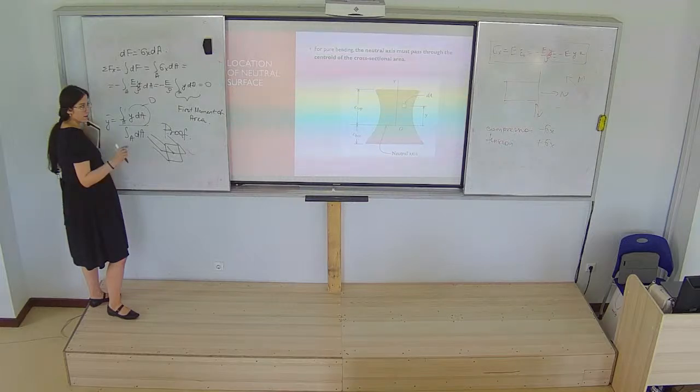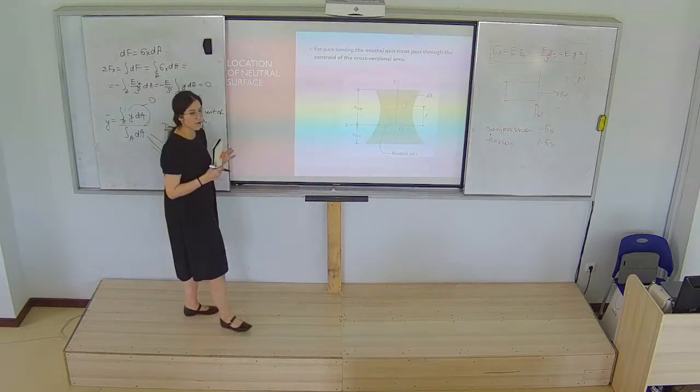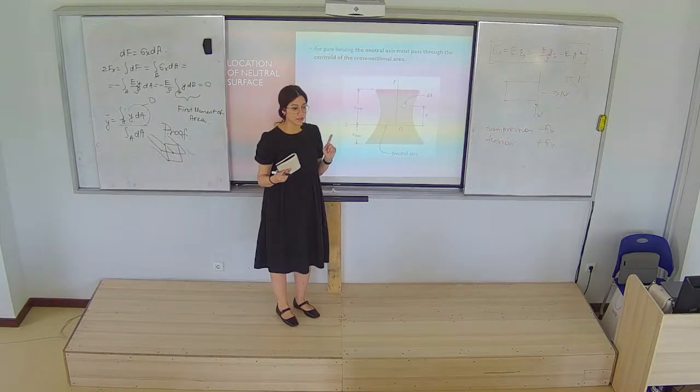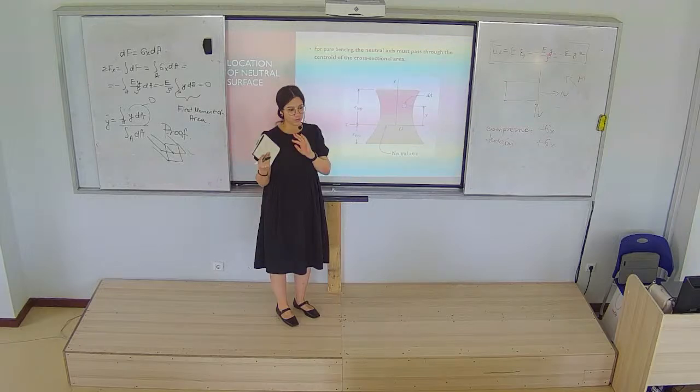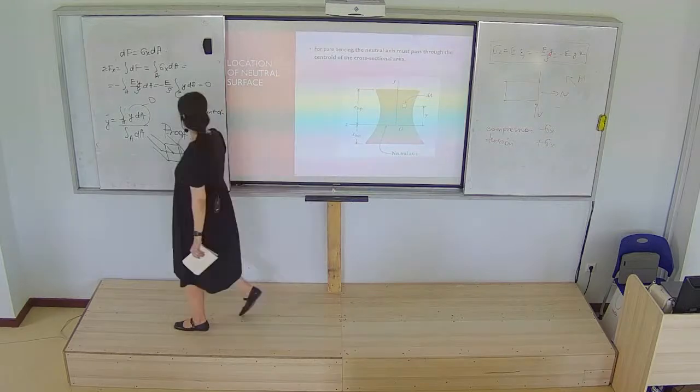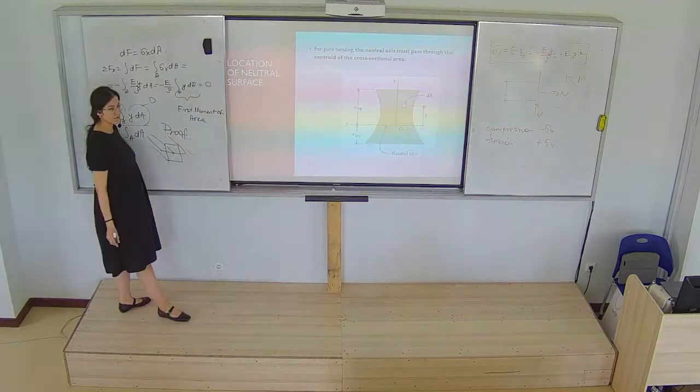We will have exercise when you are given the cross section. First step is to find the center of mass of the body. Okay? After finding this one, you can decide where our neutral axis is placed. It will be the same line as our center of mass.